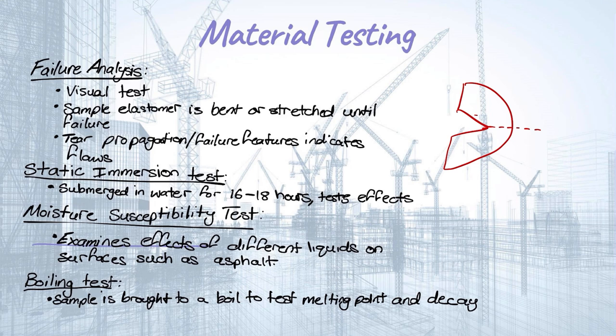Static immersion test. So this is testing how a material reacts when it's submerged in water. So you submerge it in water for 16 to 18 hours, and you test the effects such as, is it starting to decay? Does it expand substantially? Is it weakened afterwards? And things like that.